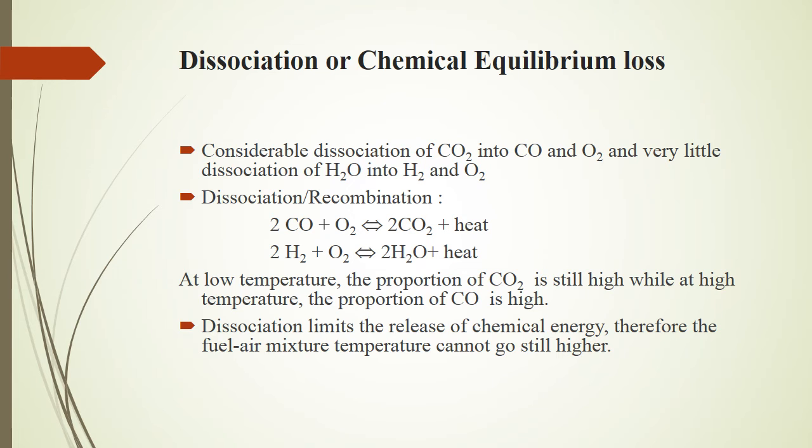At low temperature, the proportion of CO2 is high, while at high temperature, the proportion of CO is high. For this reason, the fuel-air mixture temperature after combustion cannot go still higher because dissociation limits the release of chemical energy.